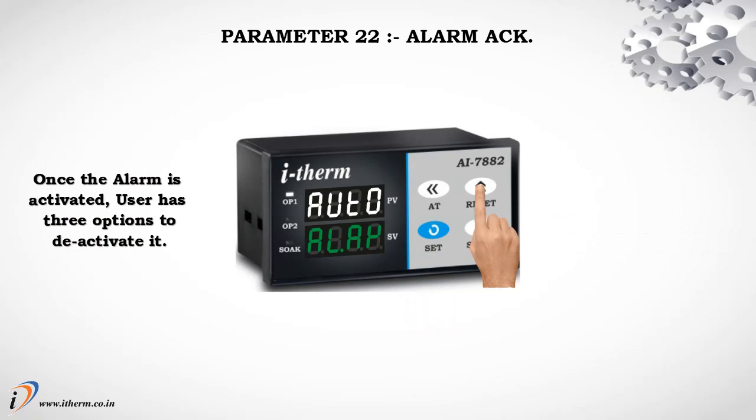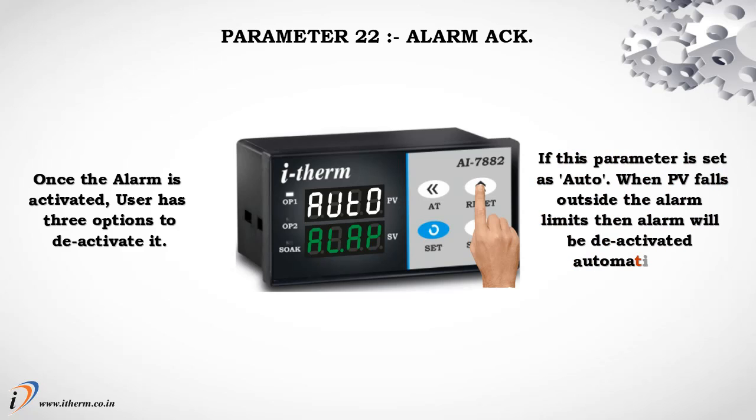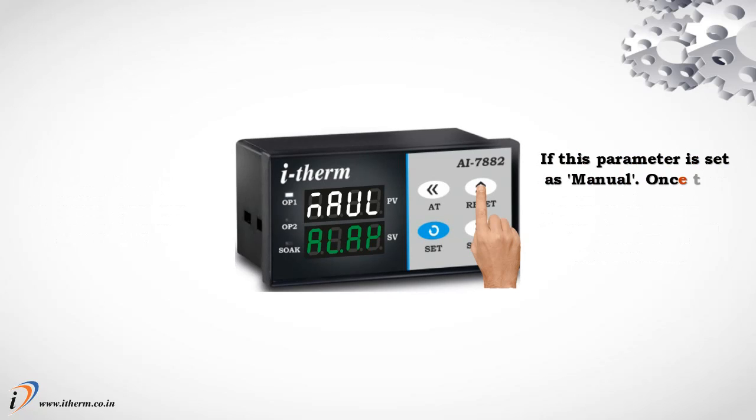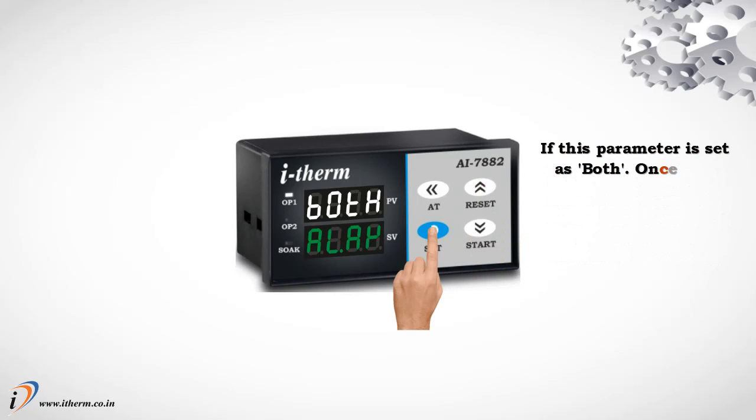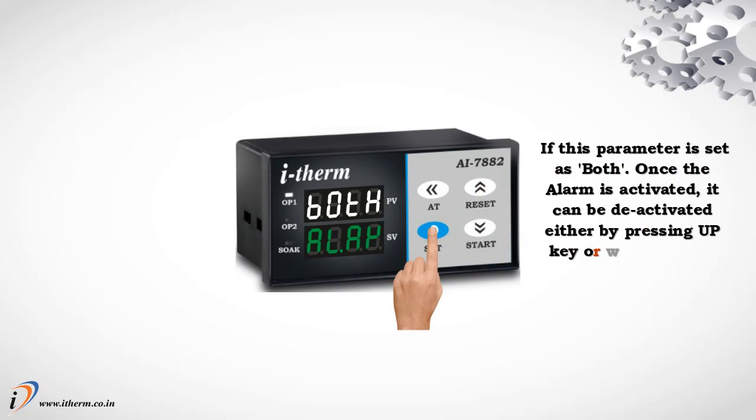Once the alarm is activated, user has 3 options to deactivate it. If this parameter is set as auto, when process value falls outside the alarm limits, then alarm will be deactivated automatically. If this parameter is set as manual, once the alarm is activated, it remains activated until acknowledged manually by up key. If this parameter is set as both, once the alarm is activated, it can be deactivated either by pressing up key, or when process value falls outside the alarm limits.